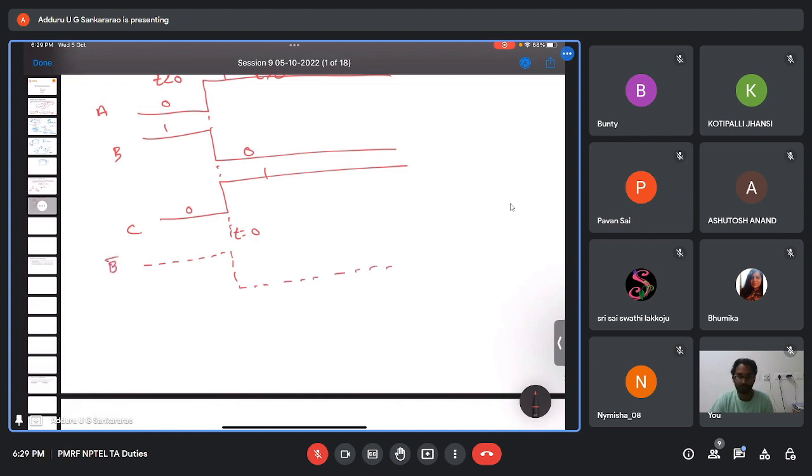It is the inverse operation of B, so it is something like this, but there is a propagation delay of 20 nanoseconds. So instead of changing immediately when B is applied, B bar will change after the 20 nanosecond propagation delay. At t equal to 0, B is changing from 1 to 0. Ideally B bar should change from 0 to, sorry, B bar is not this one.